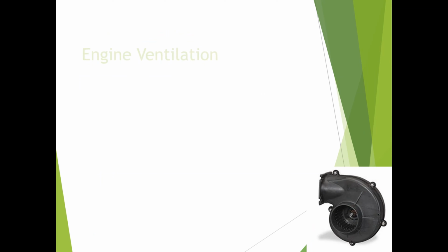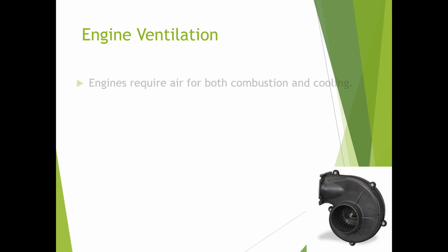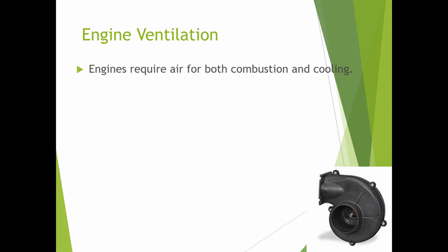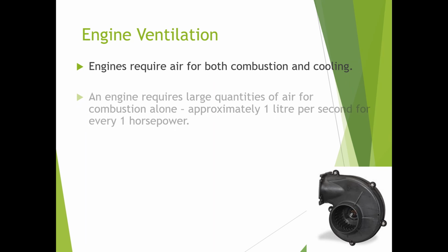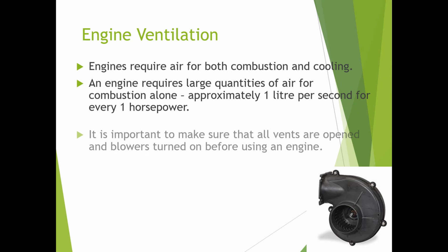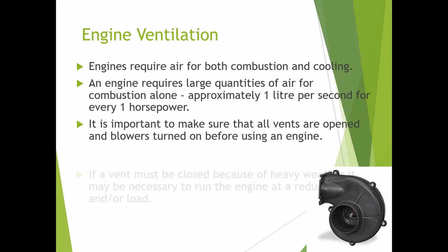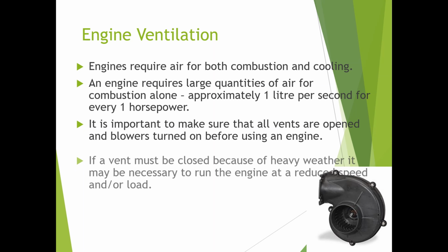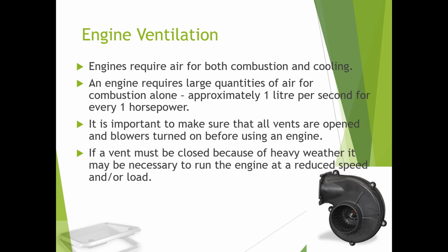Engine ventilation. Engines require air for both combustion and cooling. An engine requires large quantities of air for combustion alone, approximately 1 liter per second for every 1 horsepower. It is important to make sure that all vents are open and doors turned on before using an engine. If a vent must be closed because of heavy weather, it may be necessary to run the engine at a reduced speed and/or load.